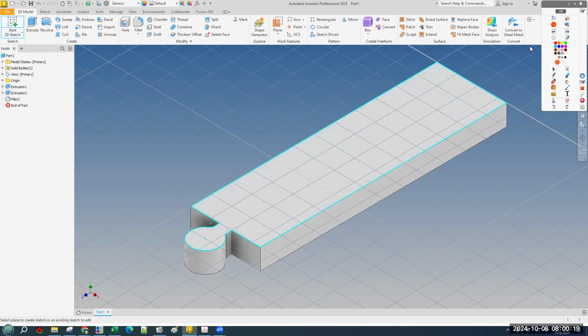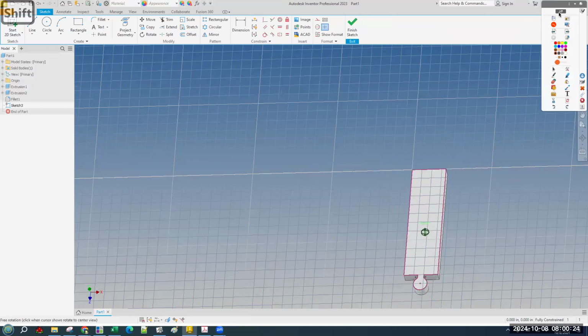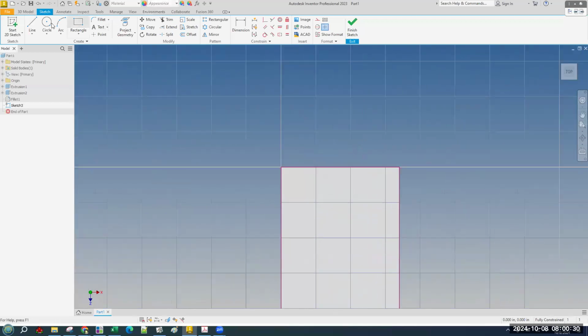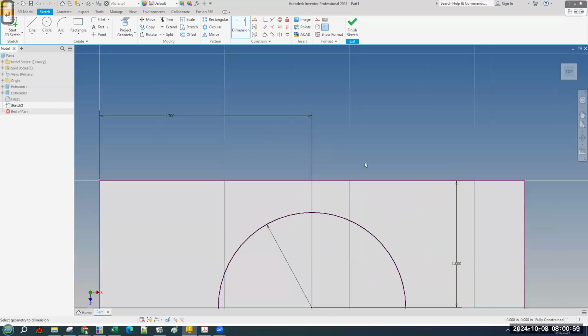Okay, so start a sketch on the top. And I'm going to go up here. You can see where I'm sketching what we already have. And so I need a circle. I need this dimension is 0.75 times 2, otherwise known as 1.5. And I still have the dimension tool. I'm going to dimension the distance from the center of the circle to the edge of the block, which needs to be 1, just like the other. And the center point to the side of everything needs to be 1.7, which you might get a soft snap there anyway. Save you a second.